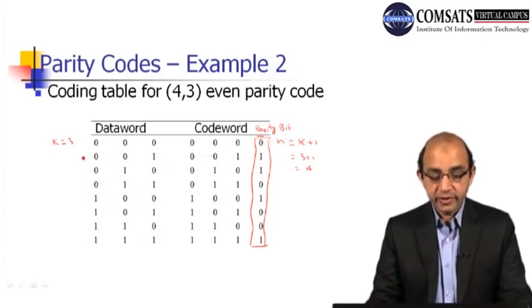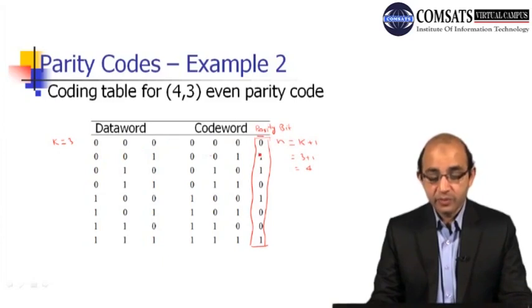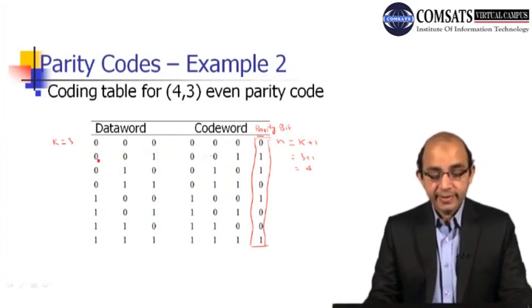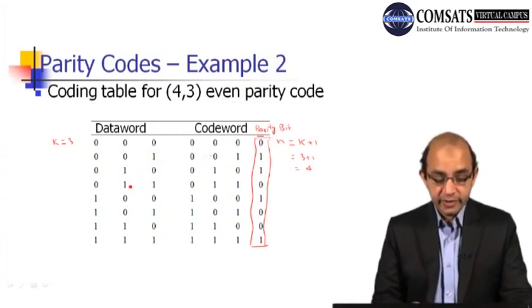You can see the number of ones. For 0 ones, there can be a debate about whether it counts as even or odd, but here you can see it is 0. Then 0, 0, 1: in order to make it even, with 2 ones, we put 1. Again 1, because the number of ones is odd here, and even here.